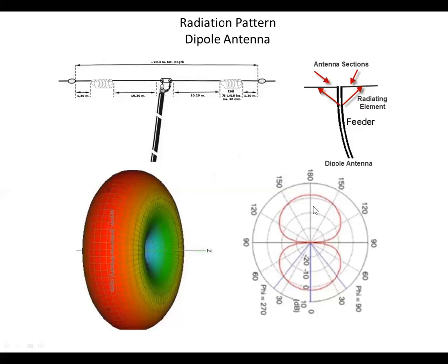But in actuality, in a real dipole, it's a fairly similar shape, but it doesn't go to zero. It just flattens out here, so you do get propagation off the ends of the dipole. So you can work on a north and south oriented dipole. You can still work folks down in Florida, Cuba, down into South America. It's just that the gain will be a little lower. You won't have as strong reception or transmission, but you can still operate off of it.